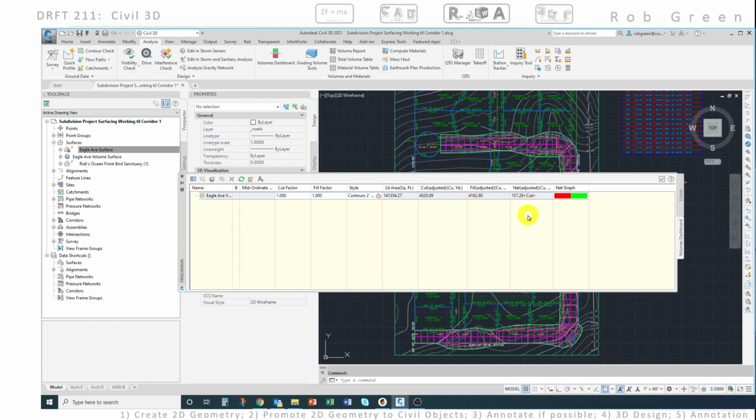And so this is 157 cubic yards. And quite honestly, we would like to have as few dump trucks or as few trucks come in as possible. So 157 cubic yards would be something like 10 small dump trucks, or, I don't know, some of these larger items, it might be 5 or 6 trucks. So we'd like to do a little bit better than that, and we will pick up on that task in the next video. Hope this is helpful, and we'll see you in chapter 5.